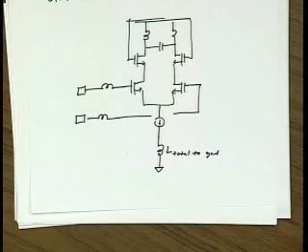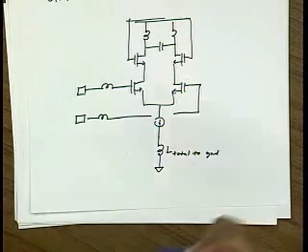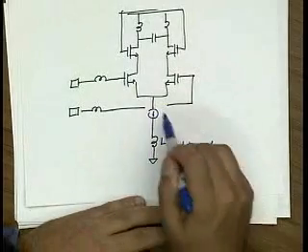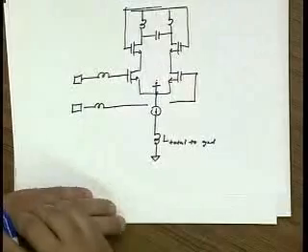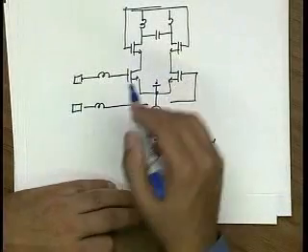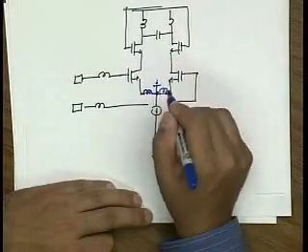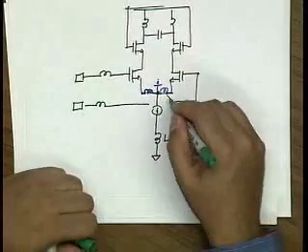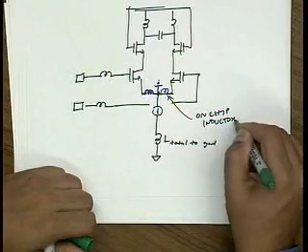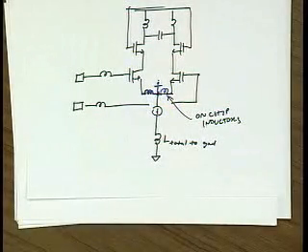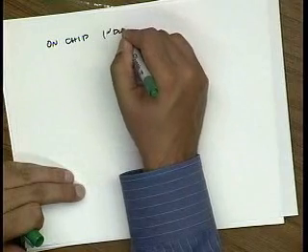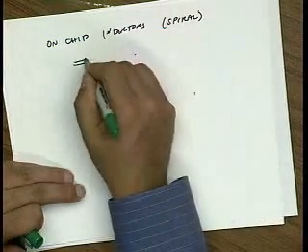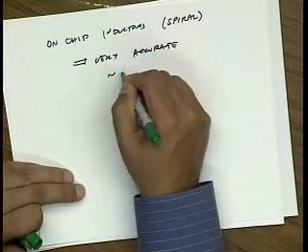Now the nice thing about a differential version of the LNA is the inductance on the source side here, on the coupled source side, doesn't matter because on chip this is a virtual ground. And if I want to degenerate these devices, I would actually just put physical inductors in the layout. So these would be on-chip inductors. And the nice thing about on-chip inductors is that they're very accurate. Their values can be very precise. It just depends on layout. So on-chip inductors, usually spiral inductors, are very accurate, let's say on the order of 3%.